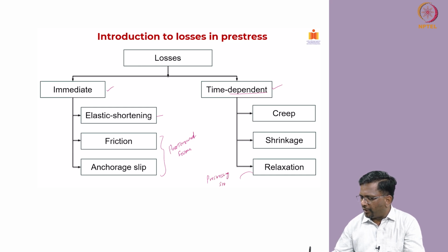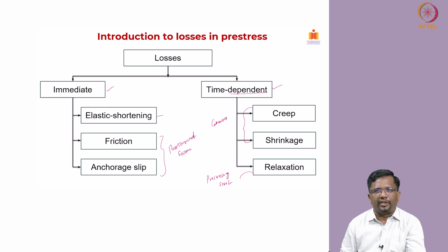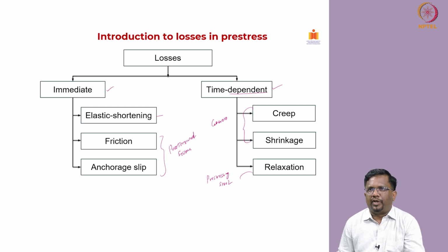This is a phenomena related to steel. These two phenomena are related to concrete. So, concrete undergoes creep and shrinkage, and pre-stressing steel undergoes relaxation. So, we have to account for all of these effects.